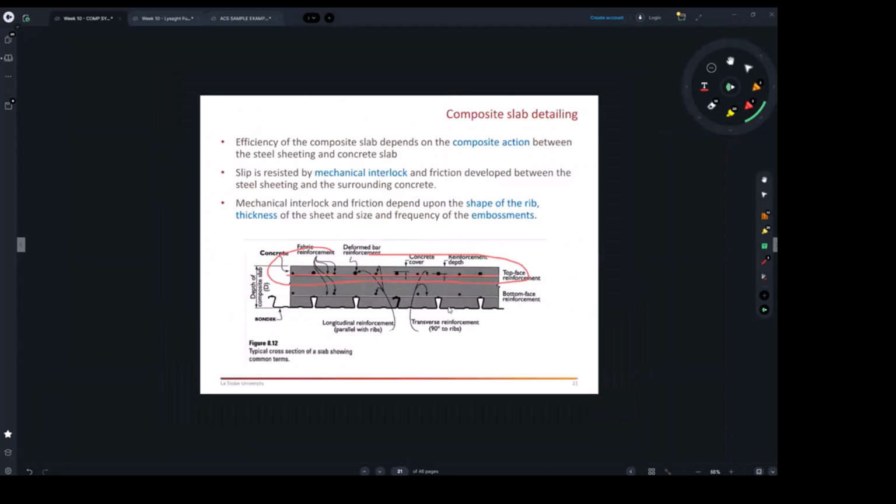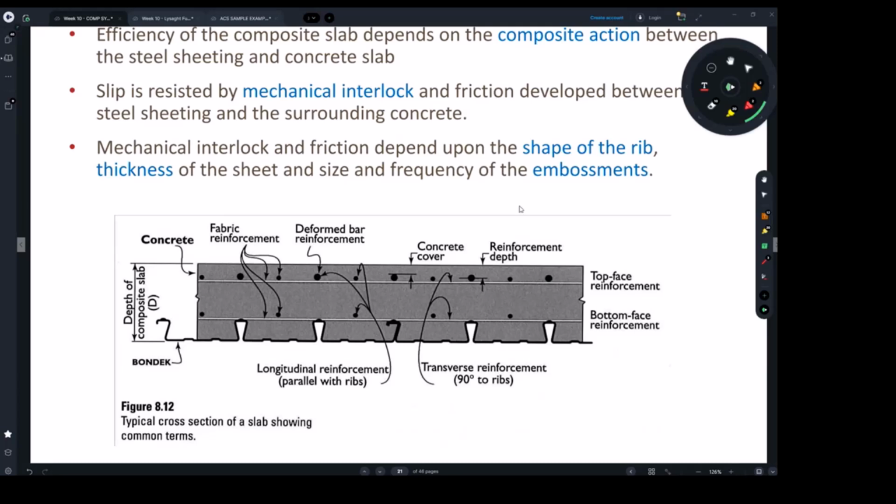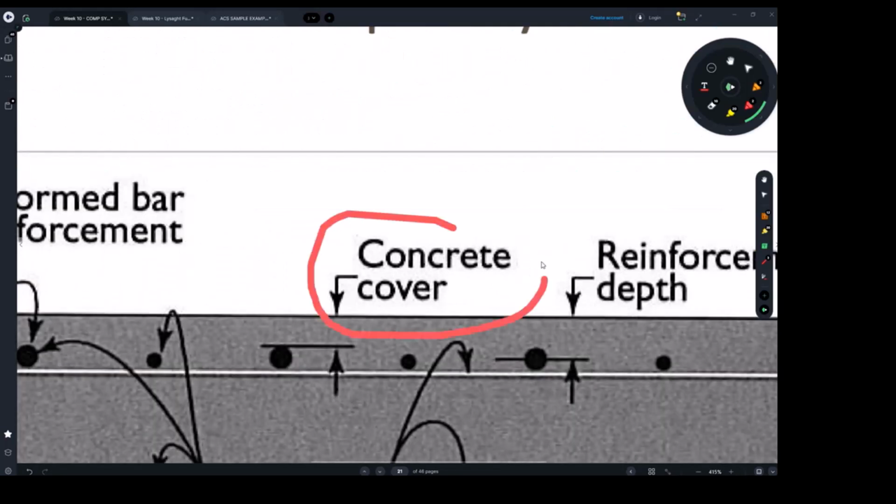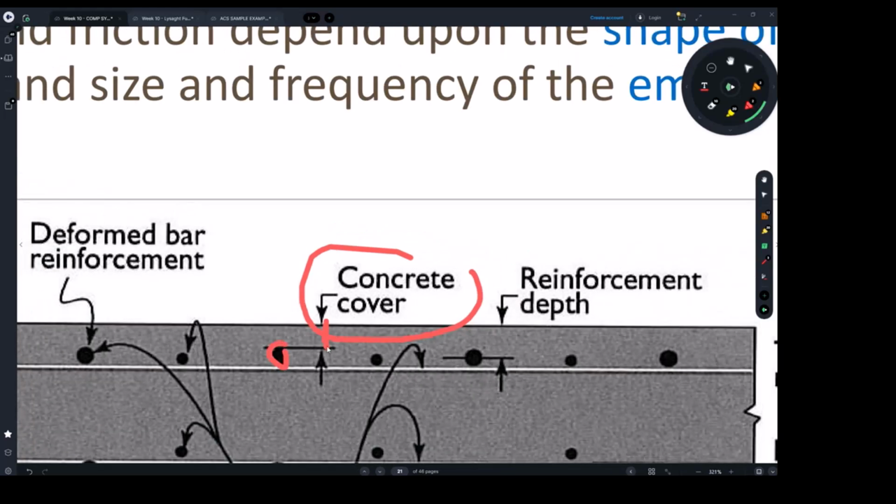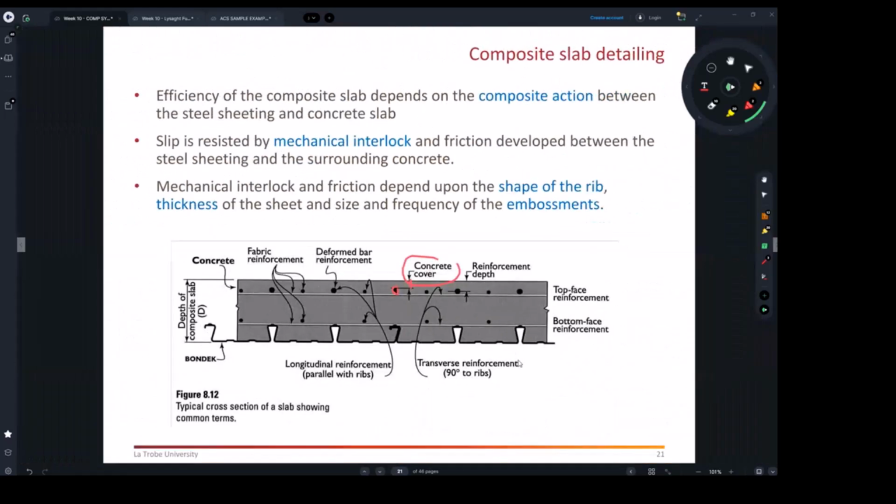Sometimes we have two-way slabs if you really need to, but that's a different story. All right, so I think I've explained most of what you're seeing here. We always need to respect the cover. There is always cover between the main bars and the top of the slab, etc. So what I want to get to is there are tables which will help us to determine the quantity of steel required, whether top or bottom, for our selected slab.